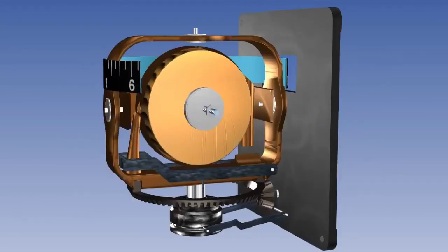The air-driven DGI incorporates bucket-like features around the perimeter of the gyro rotor, and an engine-driven pump creates a partial vacuum in the instrument case, which allows cabin air to be drawn in through an air jet, or in some cases twin air jets, to drive the gyro rotor, as we can see here. The air jet not only spins the rotor, but also maintains or ties the rotor axis in the yawing plane of the aircraft.